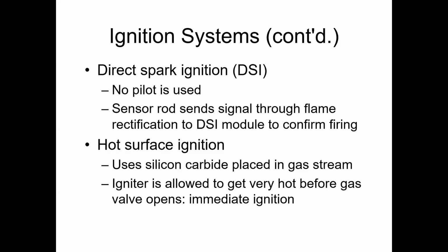They take in voltage, hold on to an incredible amount of voltage, and then send it back to neutral. And that holding on to it, that high resistance, allows it to heat up and get to a high enough temperature so that we have ignition take place. We can have that 1200 degree ignition without having to have a pilot flame or anything like that.